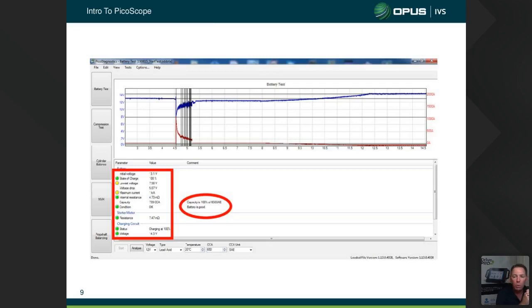It is a lot more accurate than what we find on those handheld battery meters, the capacitance type ones. I've used the Snap-on ones, and they are very good, but they are capacitance. They use an algorithm based on surface charge and discharge. Again, similar sort of technology to what Pico is using. I just find the Pico stuff a little bit more accurate. It's far more accurate than the ones you buy from the battery companies, with a little printout scroll on the end. They're good if you sell batteries, because they will tell you every second battery's failed and you need to replace it for the customer, which is great for profit, I suppose.